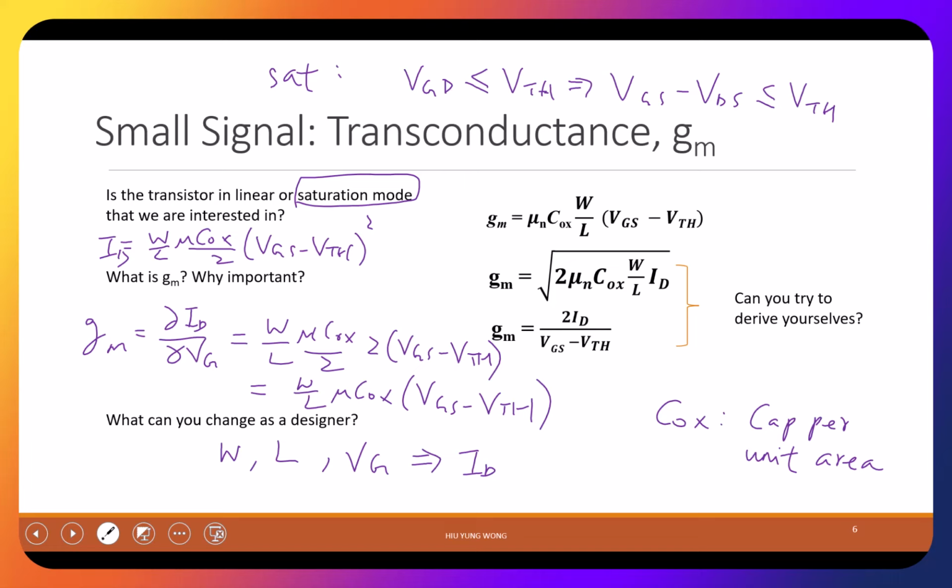Yeah, that should be called just a simplified version. Because you don't want to turn off the drain side, right? You want to have pinch off to have saturation. Pinch off means it doesn't. So VGS smaller than VTH means you cannot turn on the channel on the source side, right? Yeah, it's correct. Think about what I just said.